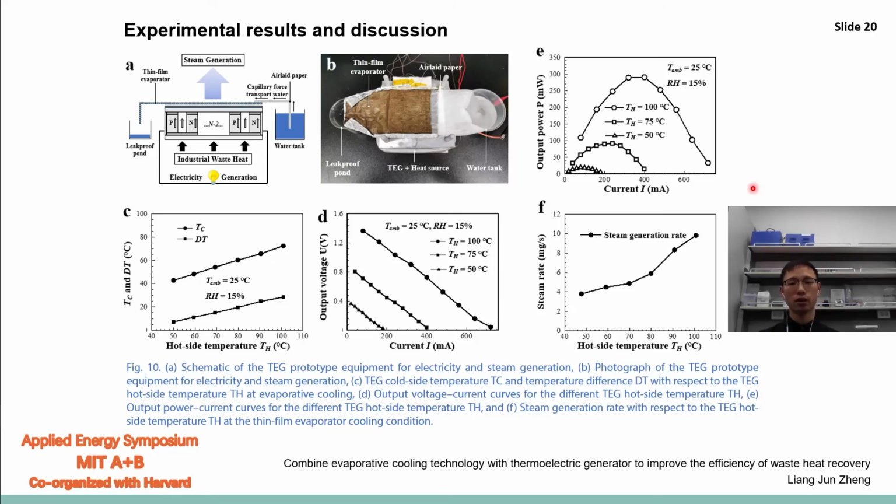By looking at the results C, D, E, F, we find that the output performance of the TEG is even better than the syringe pump case. So we hope this result shows the evaporative cooling method is an effective method to enhance the performance of the TEG, even compared with the traditional heat sink cooling method.